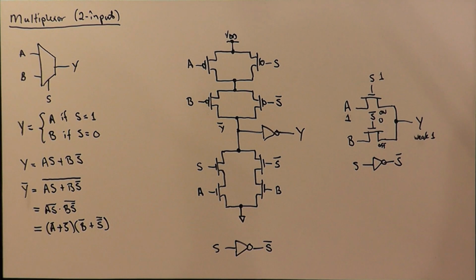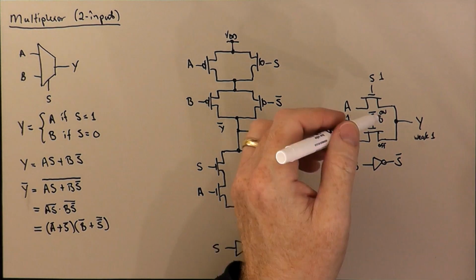because that's going to be possibly in the range of 1 if we were to follow this up with, let's say, an inverter or something like that, or a double inverter buffer, so that it would restore the logic levels. But that 3.5 volts on a 5 volt supply is going to mean that that first inversion stage would be probably drawing a fair amount of static current, because both the PMOS and the NMOS transistor are going to be on partially, up in strong inversion. So that's the real problem with this scheme.